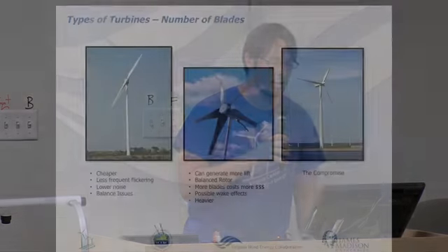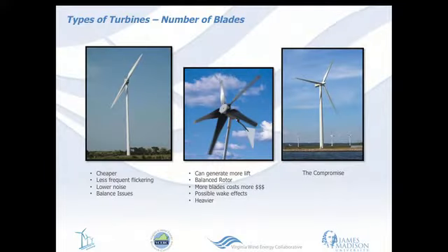A common question that we run into is, why do you normally see wind turbines with 3 blades? It's mostly an engineering reason. I'll start with this: you do see large-scale and small-scale 2-bladed machines. Those still exist. And that's because they're generally cheaper. Less materials means less you have to spend to make them. And when you're talking about an 80-meter blade or so, that can be a significant cost to not have to spend.